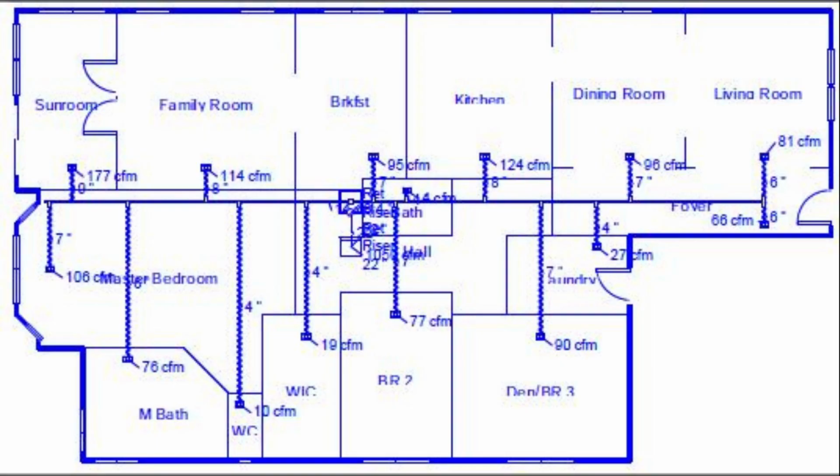Equipment placement. Locate the furnace or heat pump air handler as close to the center of the house as possible. Supply grill placement. Locate supply grills close to interior walls of rooms where possible. Side wall registers are preferred. Grill selection. Select supply grills that provide sufficient throw to reach exterior walls. Air supply considerations. Avoid supplying air to low-load interior spaces such as closets and powder rooms.